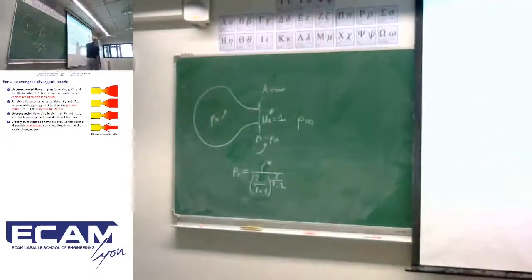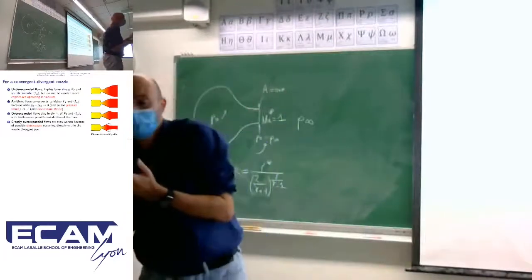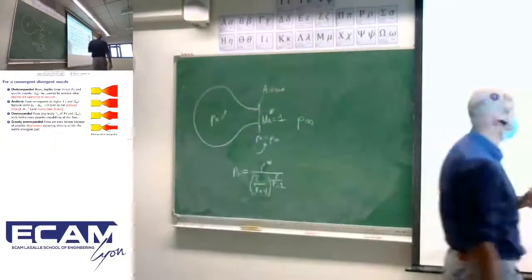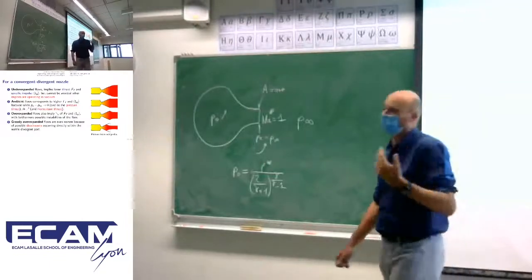This situation happens depending on the altitude. So basically, this one is low altitude. This one is supposed to happen at only one altitude, the one where the pressures are equal. And this one is at high altitude. And this one corresponds to degraded behavior with lower propulsion efficiency, but it's not really possible to do it another way because it means you need to change the geometry of the thruster. It exists, but it's only on prototypes, and it doesn't work in the long run. This one corresponds to, theoretically, the best situation, the best performance of the engine.